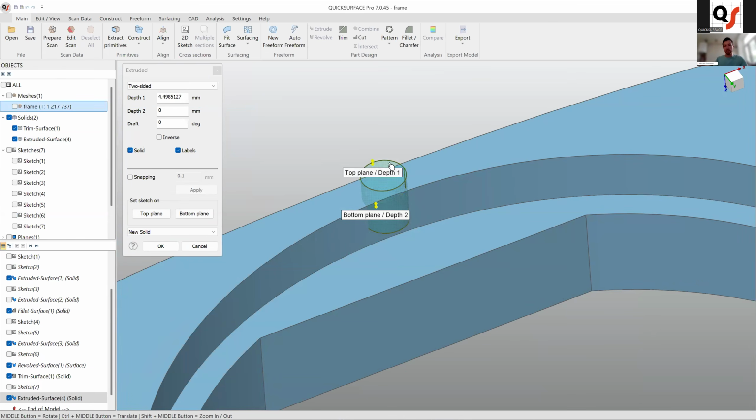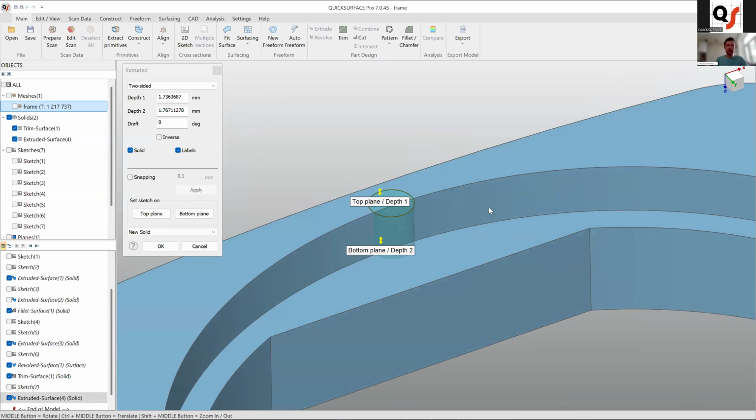At this point, you select how far you want to extrude this by holding Control and mapping to this top surface. Just eyeballing, I see that it intersects the next surface like this, so I like it here. And now you can choose what you want this extrusion to be: a new solid, or you want to combine it, or you want to cut it from the visible solid. Basically, for these options to work, combine and cut, you have to have a visible solid that is intersected with your extrusion. Otherwise, it won't work.